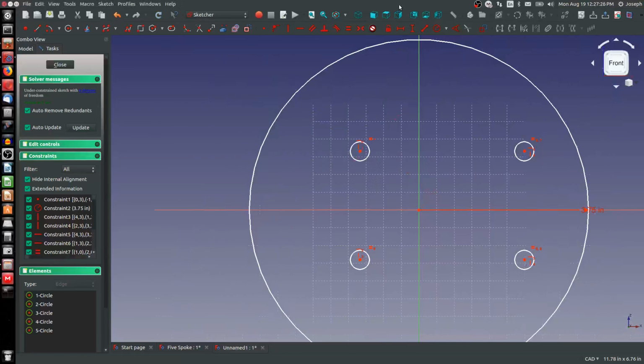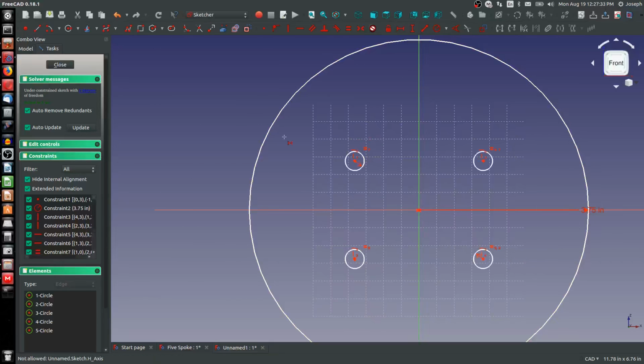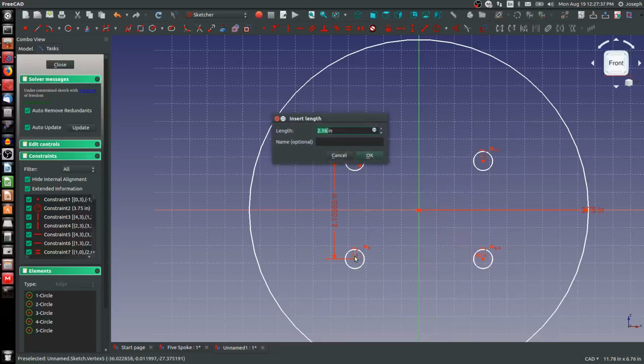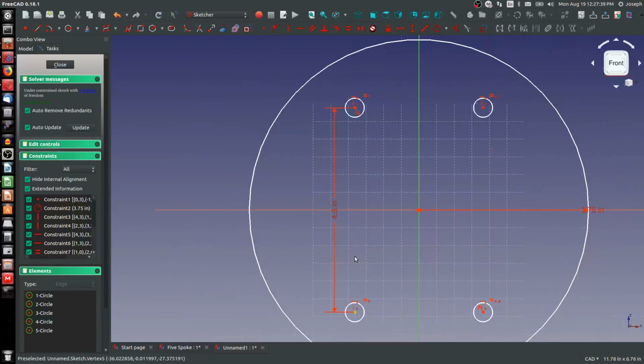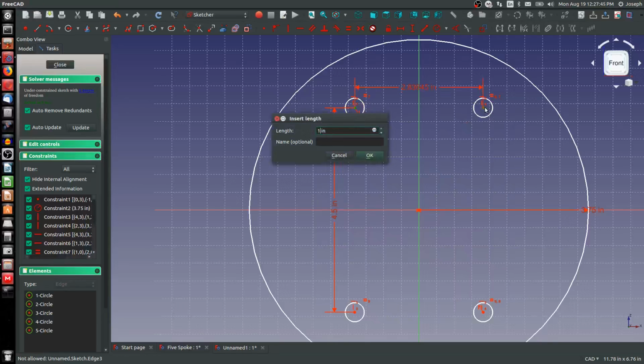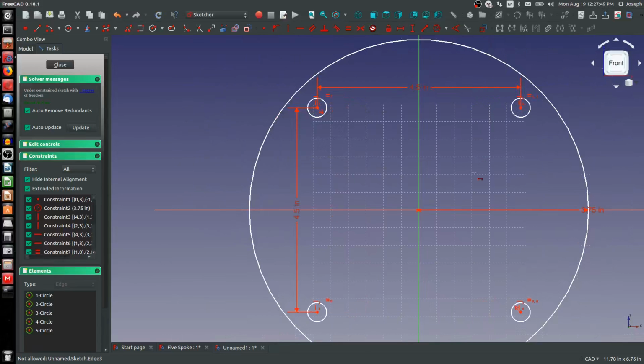We'll add a symmetric constraint to center it on the origin. And now Shift V. We'll give that 4.5 inches. And H, 4.5 inches. So this will be a 4-lug, 117.3 millimeter wheel. This would fit on a classic 80s car. You can make whatever bolt pattern you'd like.